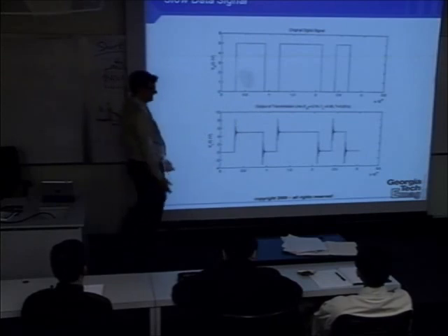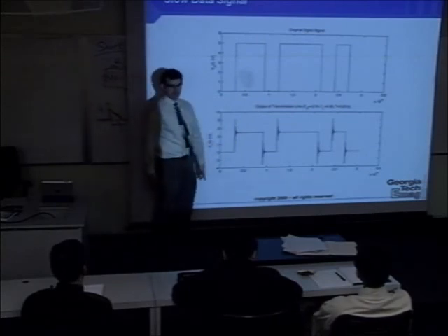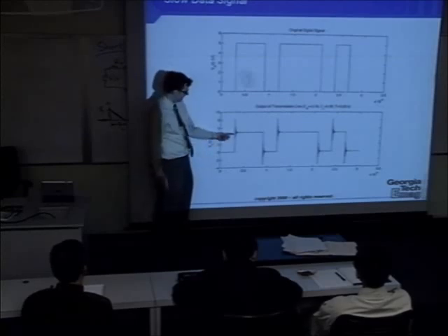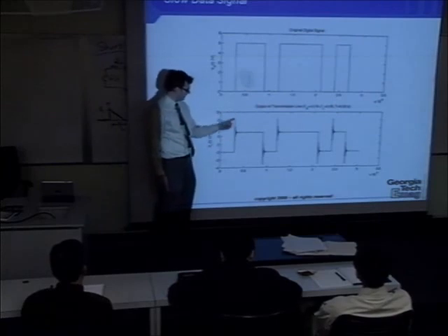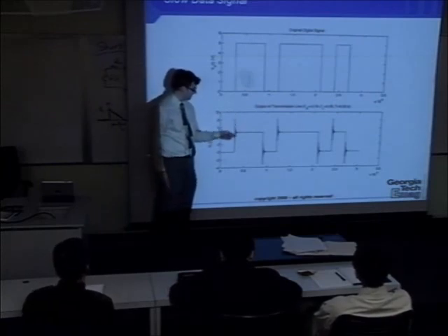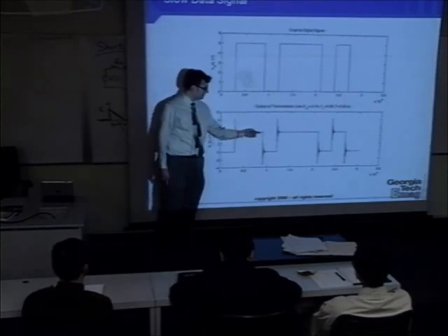So now you can see the size of the pulse is actually much larger than a transit time in this scenario. Look at that. I get ringing on the front side, where I get the huge jump up and then jump down, jump up, jump down, oscillating, decaying behavior, and then finally it settles into a nice DC value.